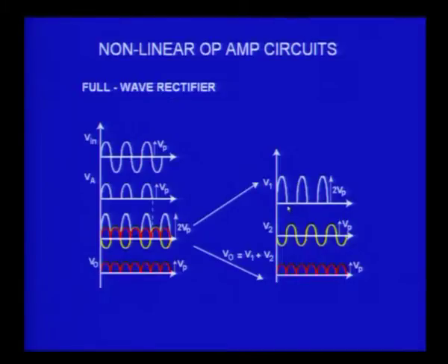If I come to the second half cycle, there is only one peak voltage in the upward direction, and there is nothing from the other input, and therefore when you sum them, you again get a peak voltage here in the same direction. So, like that for each wave you get only a net output peak voltage, and therefore when I monitor the output voltage of the summing amplifier, I get a full wave rectified signal.